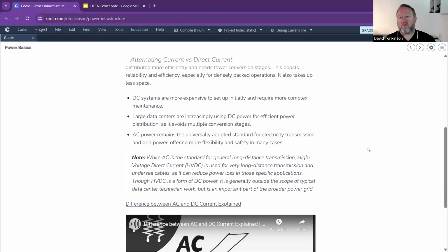And one interesting thing is that, of course, when we kick across in most data centers from our beautiful AC, from our mains lines, to our battery, which is DC, we have to convert that DC to AC to push around our data center, to then convert back to DC to actually run the silicon inside the machines. So we are literally converting DC to AC to DC. Every time we run a conversion, we are losing between 5 and 12% of that electrical current. We know where that goes. That basically goes out in heat.